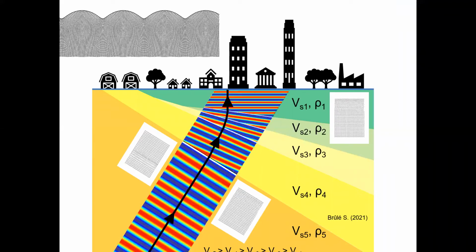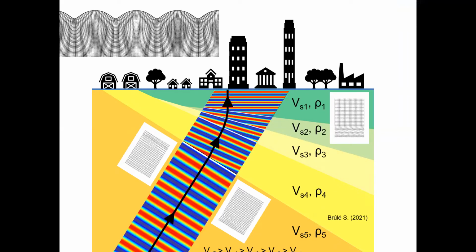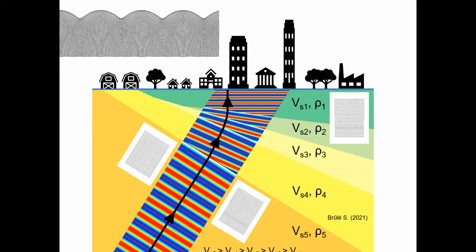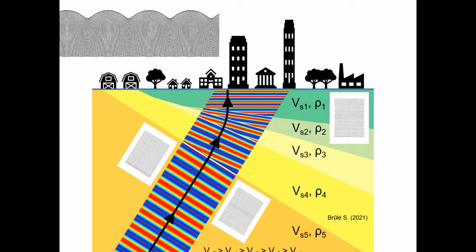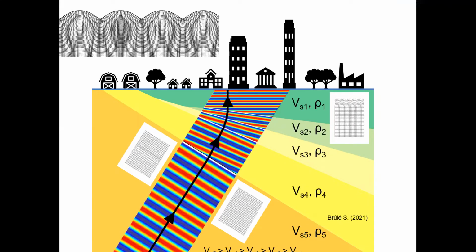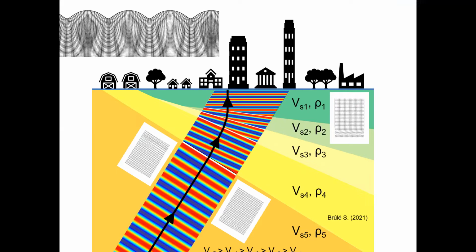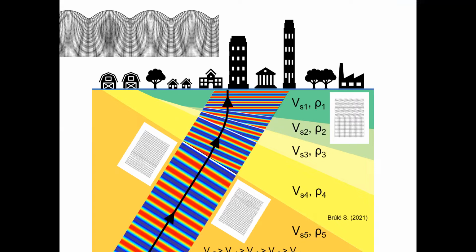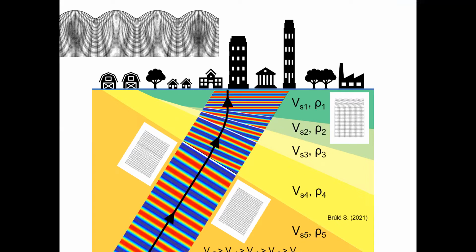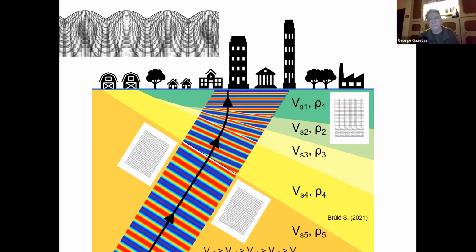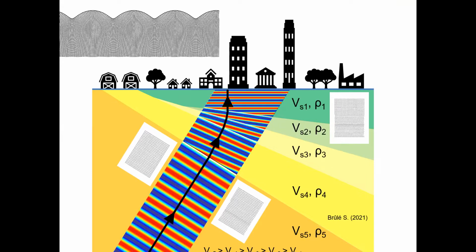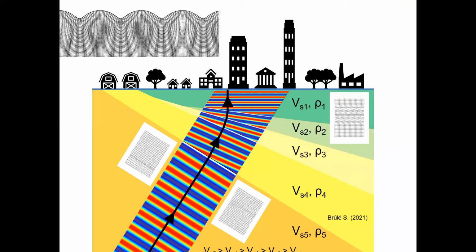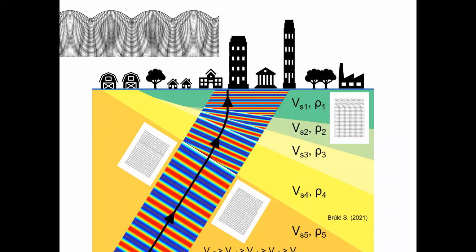If we accept flexibility for the building, it's good for the equivalent horizontal force applied to the building. But the price to pay is that flexibility means more displacement at the top of the building. So flexibility is good, but we have to take into account the amplitude of the displacement.